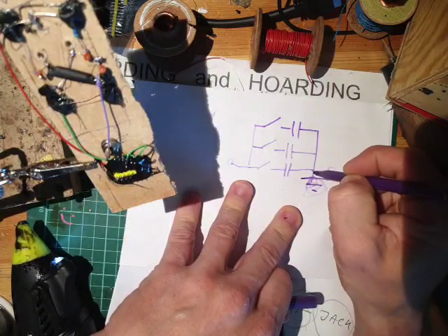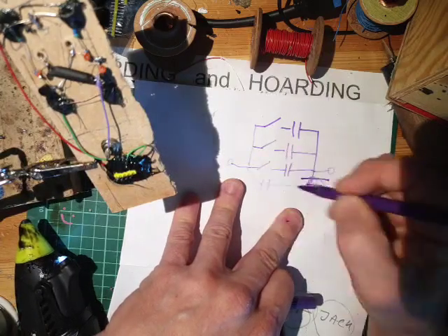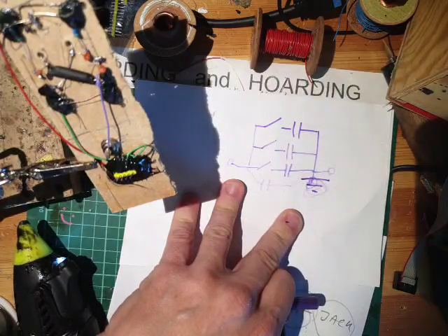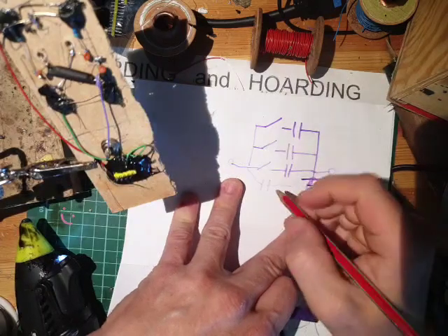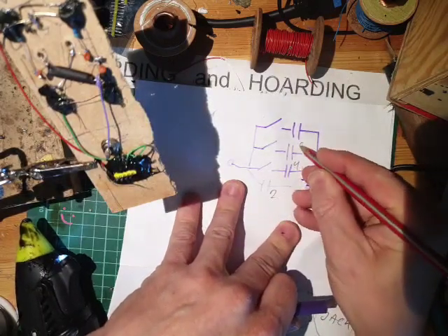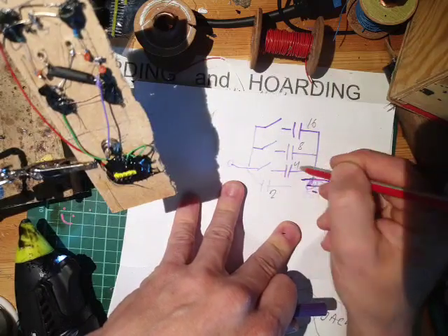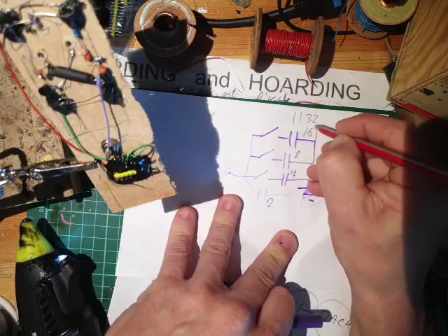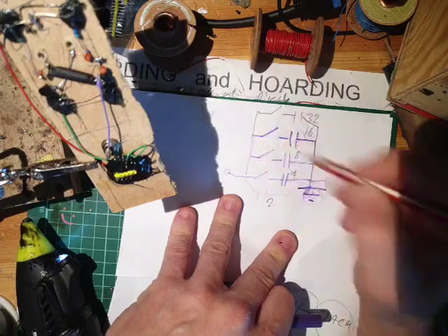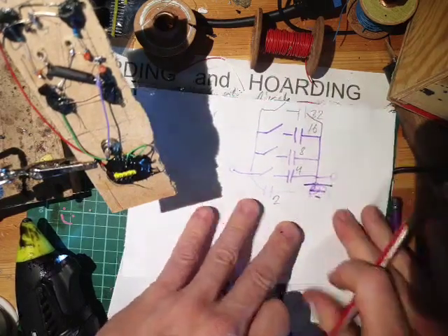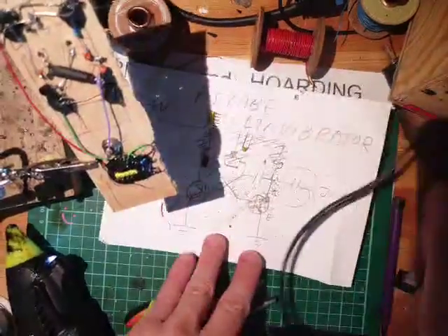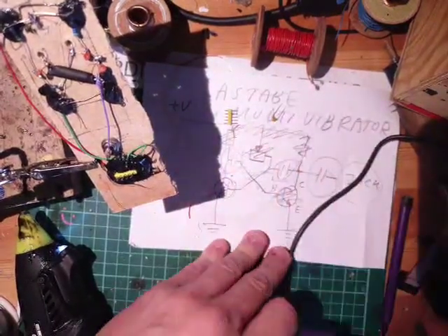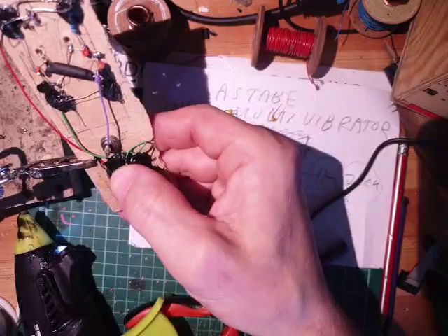And then you will have maybe one that is always on. And then if this is 1, this is 10, this is 100, this is 1000, or also you can count in binary, might be better. So if you have 2 here, you can have 4, 8, and 16, and then you can get sort of any value. And you can just go on here, put more and more on here, and then you can sort of have the possibility to switch in any value. And if you do this in both positions in this circuit right here, both here and here, then you get something that could work in a very large range of frequencies.